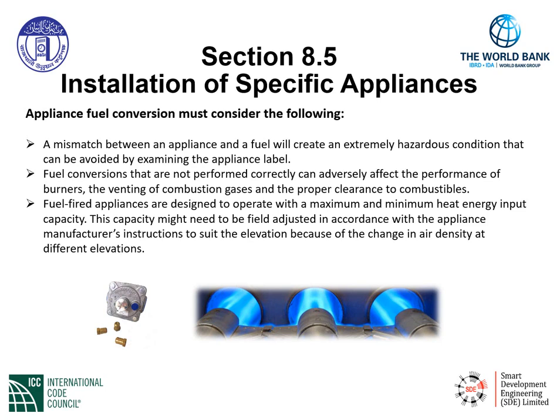When we convert appliances to different types of fuel, the manufacturer may have kits that are available. As shown in the photos below, we may have to provide or install a brand new regulator, maybe to convert from natural gas to LPG. In addition, we may have to replace the orifices or the nozzles in the burners.